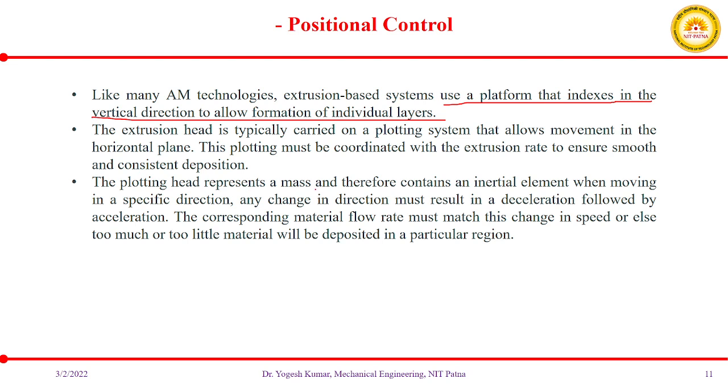The floating head represents a mass and therefore contains an inertial element when moving in a specific direction. Any change in direction must result in a deceleration followed by acceleration. Since there is acceleration and deceleration in the movement of your nozzle or floating head, you must maintain the same acceleration and deceleration in the material flow rate. Otherwise there will be a mismatch in the material quality.